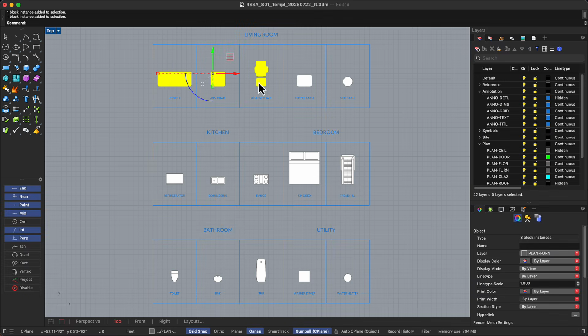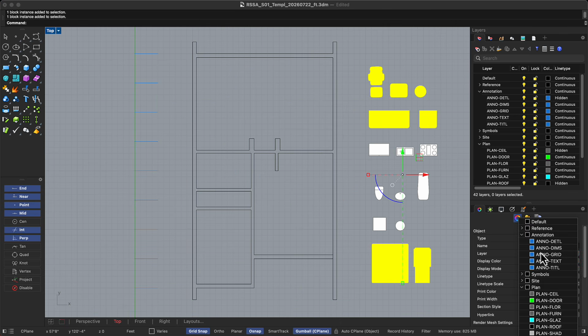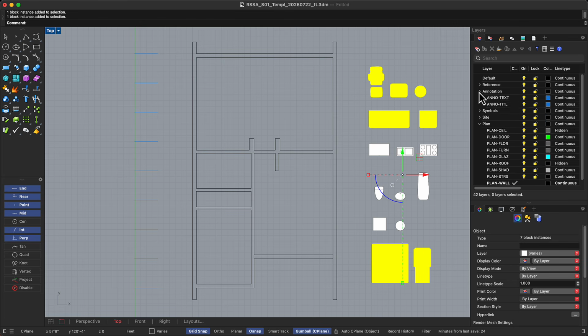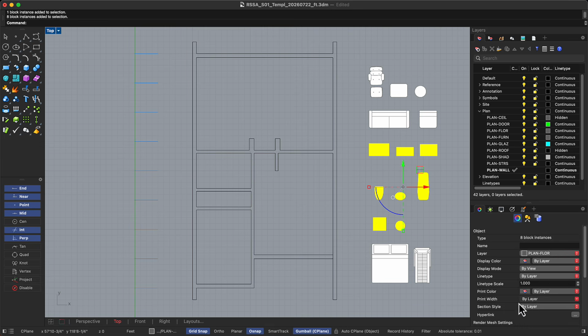Now, let's test whether the rooms can support their intended use. Copy the symbols from the template and place them on their respective layers. Place beds, desks, dining tables, sofas, and other movable objects on planned furniture. Place cabinetry, appliances, laundry equipment, and other built-in elements on planned floor.